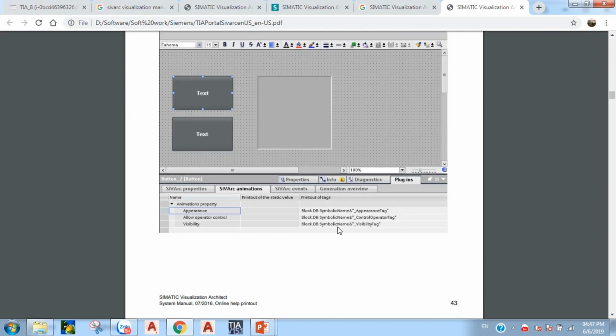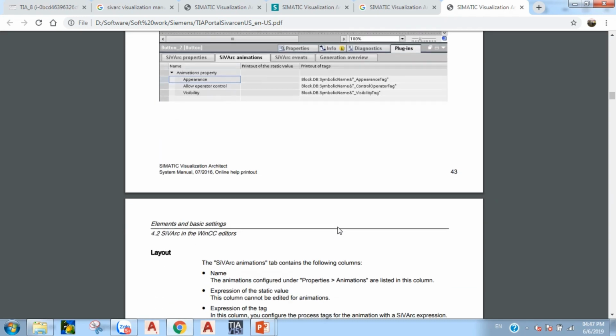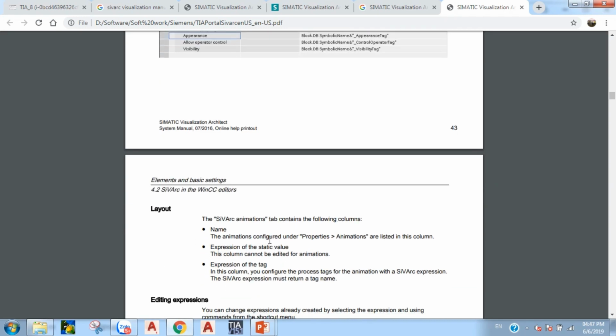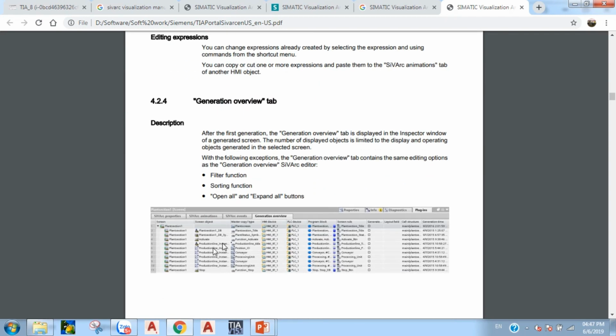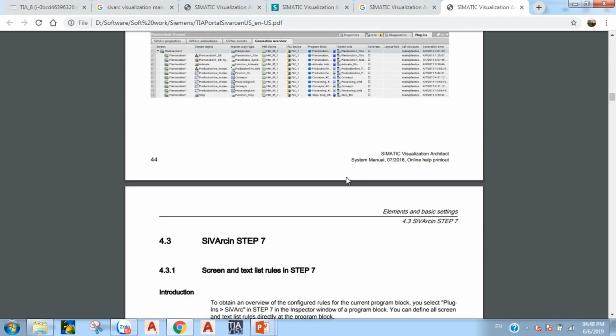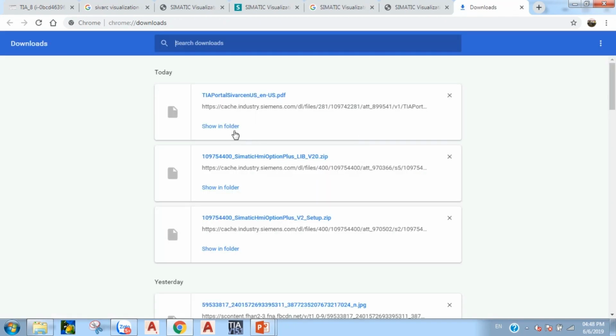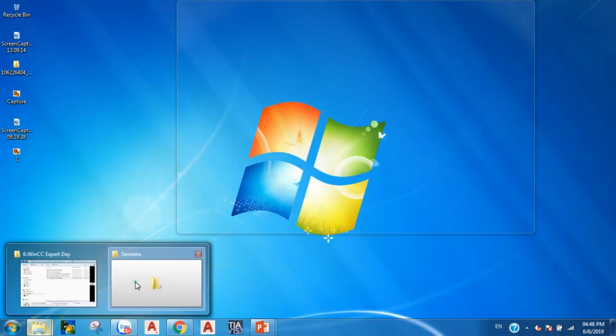In order to link that again, I use my block symbolic name, which is in that case FB underline tanks, and I add the tag element, which is in my FB tanks DB, called trend value. That's all I wanted to do.